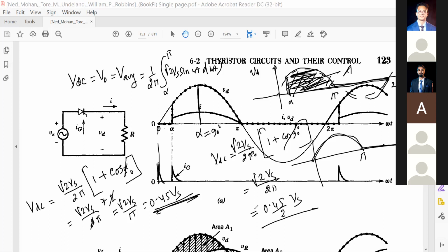So this is the wave. Then you can always generate a pulse using pulse generating circuits, and you have to synchronize with the input voltage, then you can vary the alpha from 0 to pi. So this is the phase control. The term phase control rectifier is like that. You can have the control parameter that will vary from 0 to pi. Everyone got it? Yes, sir.